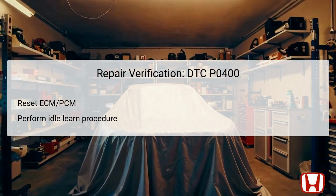Following the reset, performing the ECM-PCM idle learn procedure is crucial to help the engine management system learn the new idle settings that accommodate the recent repairs. Once these steps are taken, it's essential to conduct a thorough test drive under specific conditions to ensure that the system operates properly without returning the DTC. Monitoring the OBD status again will conclude the verification process to confirm whether the repairs addressed the initial problem effectively.